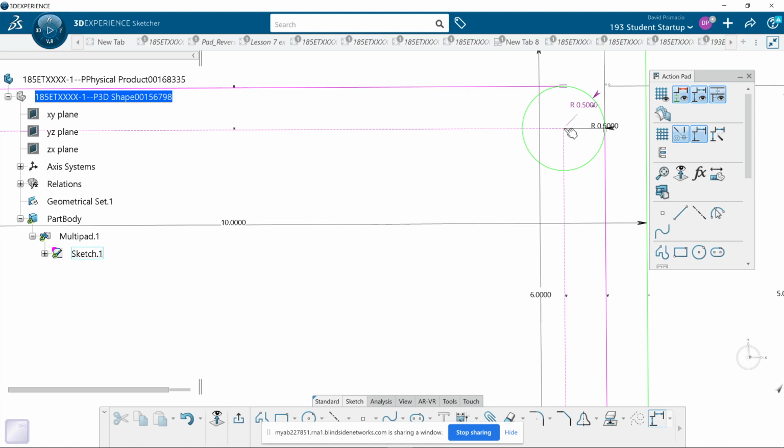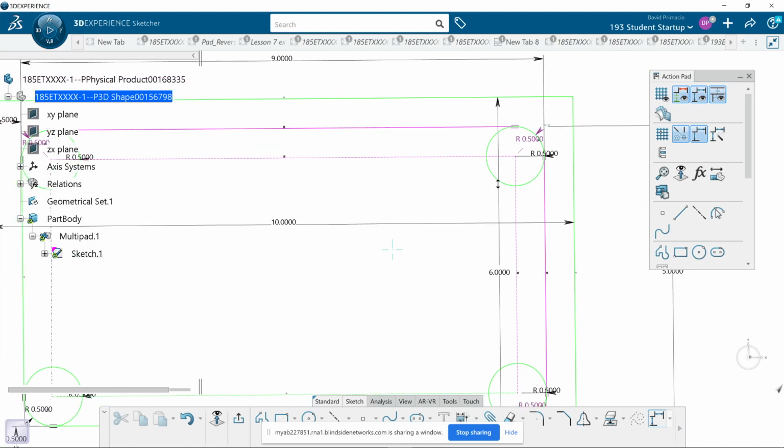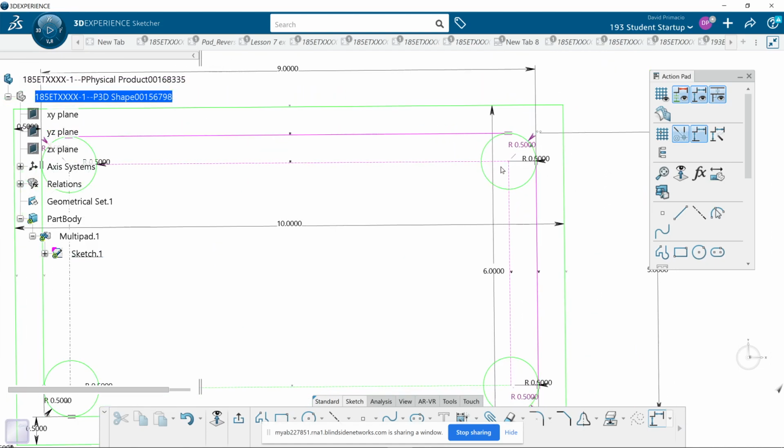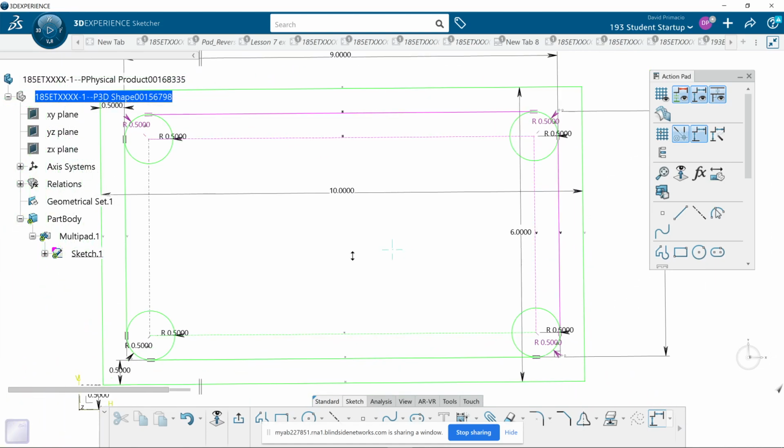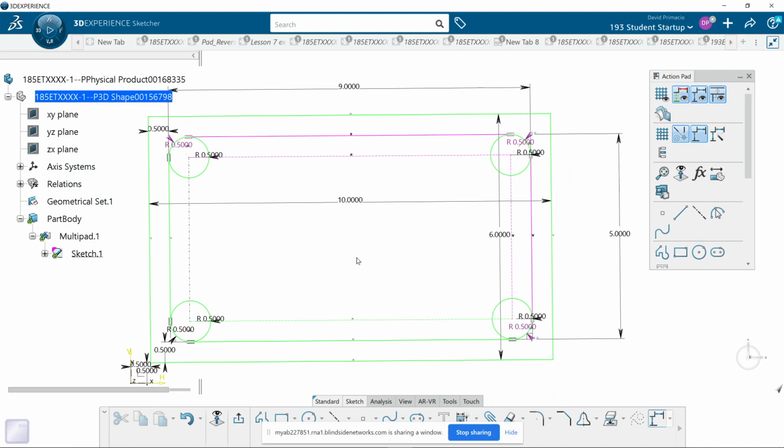Well, it's sharing one point, so isn't it adjacent? It is adjacent, indeed, but it is not tangent. So when you hear the term, you have to have tangency and you have to have adjacent. It's not in the engineering part itself, it's in the tool path. If the tool path does not have tangency and adjacent, you're going to have issues.